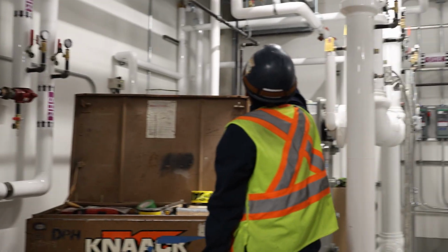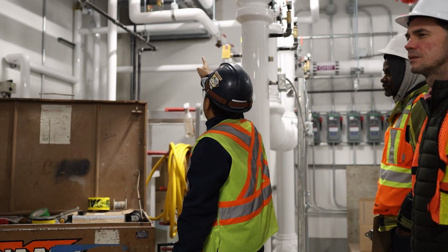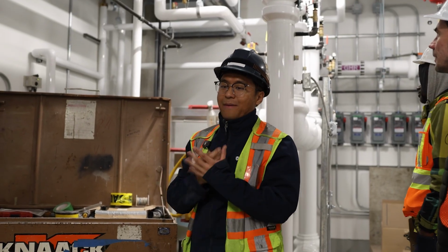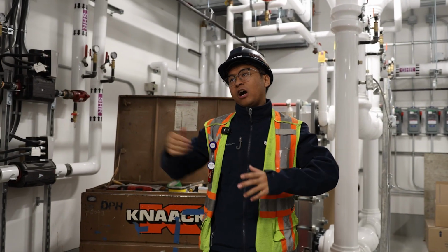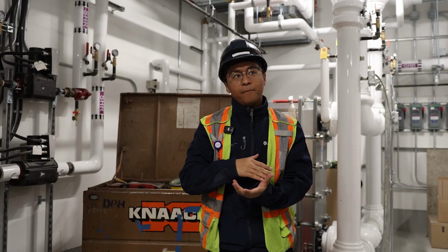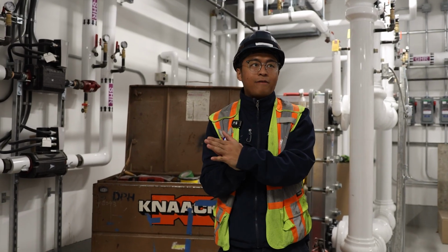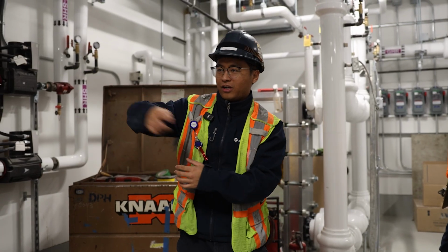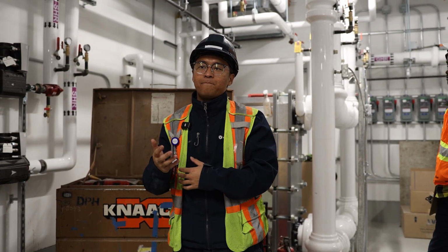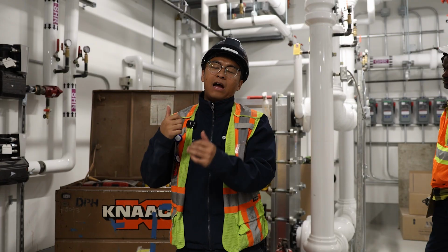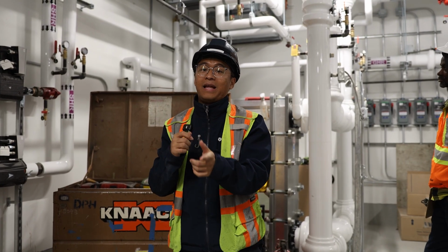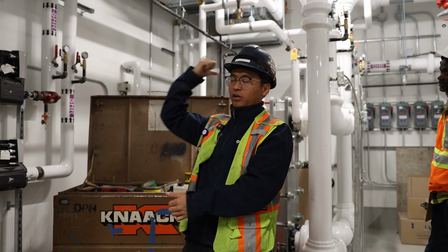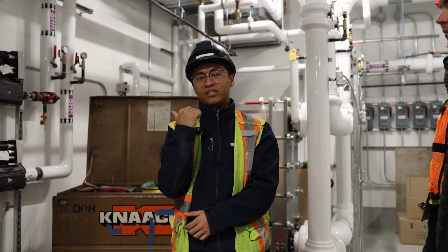And then there is a 3-way valve. So what happens there is whenever the BMS is saying the temperature coming from the solar is too cold, it will start closing the 3-way valve so that we will reuse that heat back to the solar so solar can keep up the temperature. Then we only supply the hot temperature to the domestic hot water system.